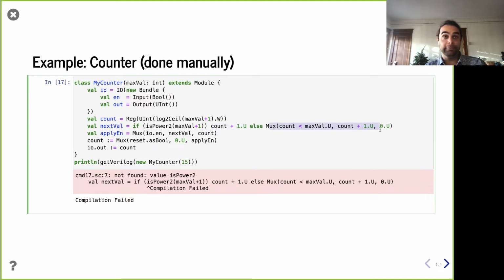So here's a way we can have a little bit of cleverness inside your generator, right? It's able to be given any inputs and do some very smart things, right? You can imagine that if you're writing a simple vanilla Verilog block, you can't quite have this kind of sophistication, right? So already you can see that the generation methodology is allowing us to have more efficient hardware and be more clever. And what's nice is it's hidden from the outside, right? The outside user of our module or generator will just say, hey, I give it a max value, connect inputs and outputs, and I'm done. And then internally we can do nice optimizations like we just showed.